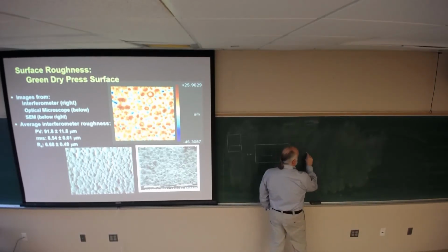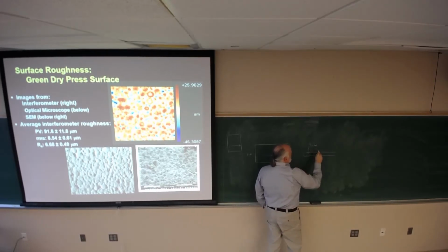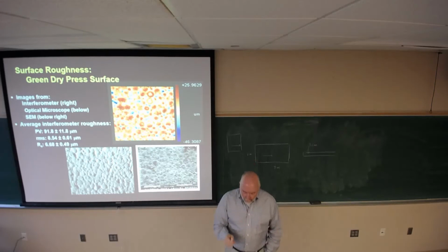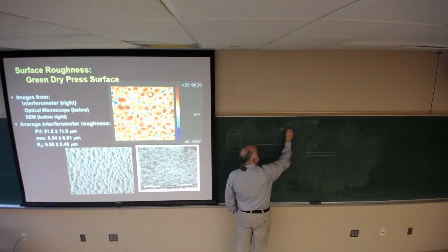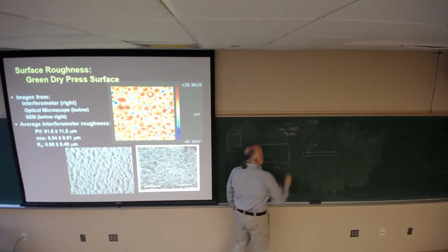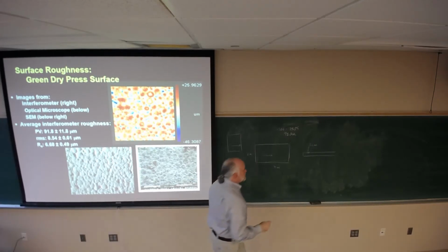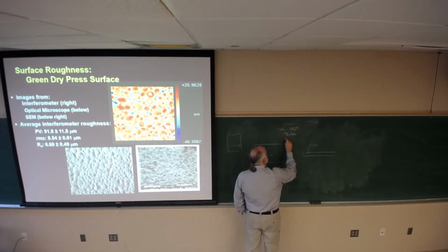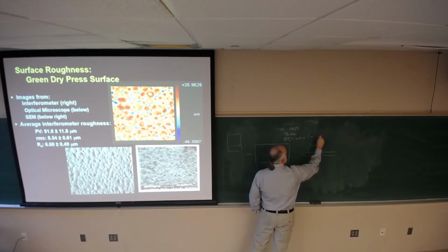If I take this tile, and I have, say, 2 centimeters, and I'm cooling that tile quickly, my peak temperature here is typically around 1200 to 1250 degrees C. It's at the peak temperature in a 50-minute cycle for about 6 minutes, which, by the way, is 0.1 hour.